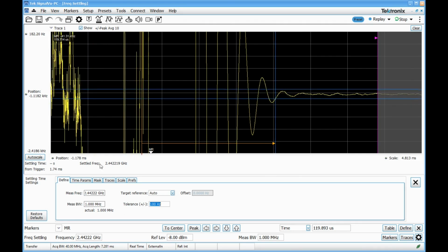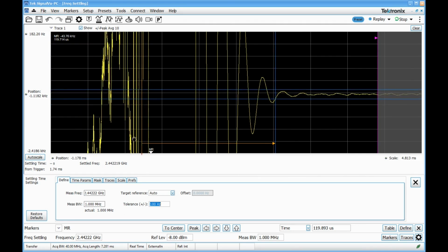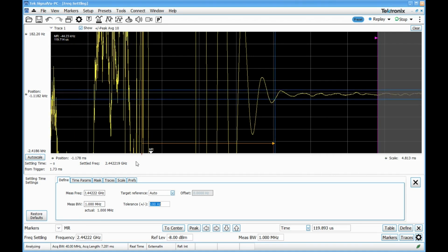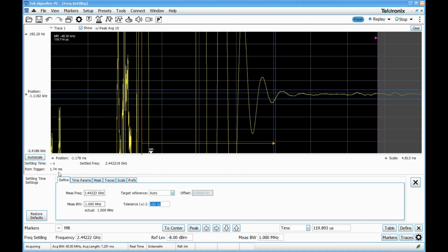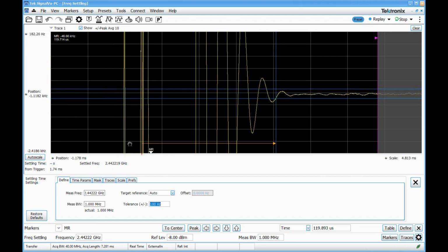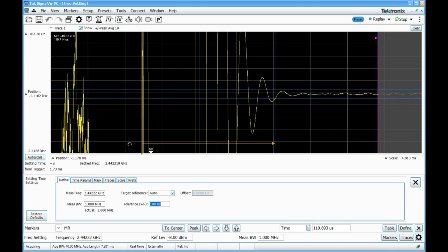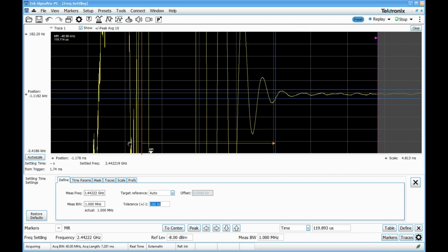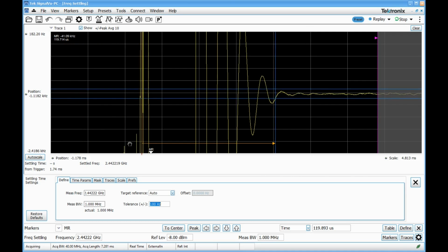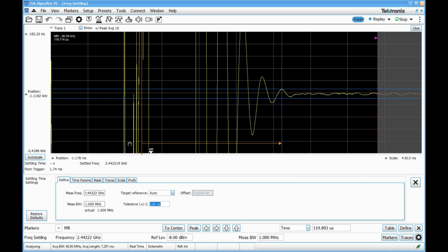And we can see that it's taking 1.73 milliseconds from the trigger to get there. And we also know from our previous result that we're about 30 microseconds longer than that to go from our starting frequency. So with these couple of changes, we've actually made a 5,000x improvement in our settling time resolution by optimizing the measurement within frequency settling.